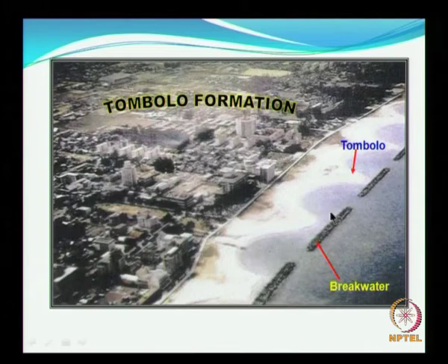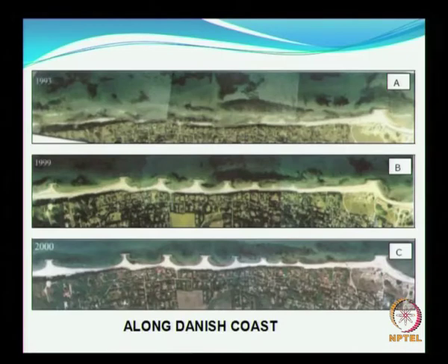You see that this can be a small bay, and this can be another bay, acting as something like a swimming pool, so you can have a relaxing beach, etc. These are some of the advantages of having offshore detached breakwaters. This picture shows, along the Danish coast, how the offshore detached breakwater has helped in beach buildup.